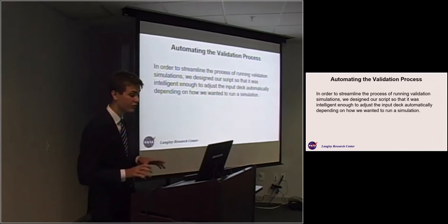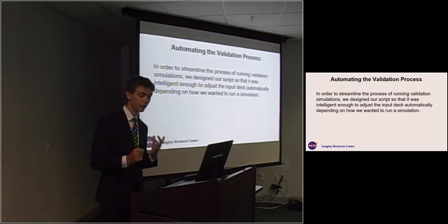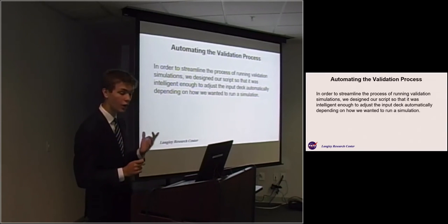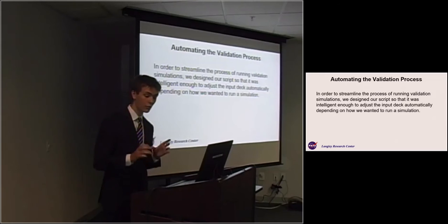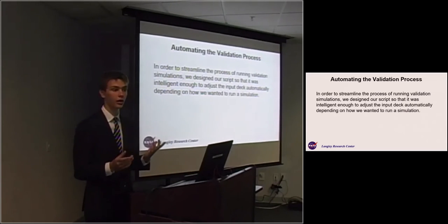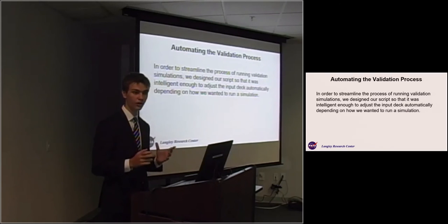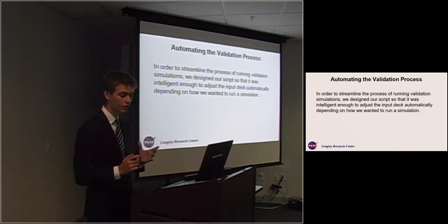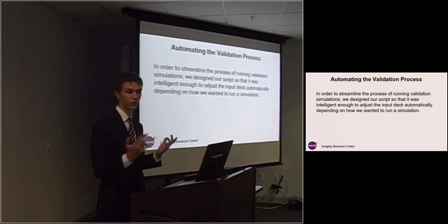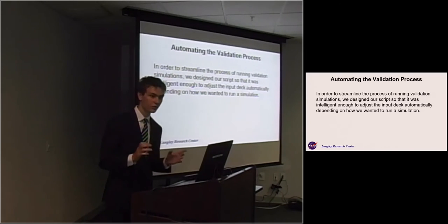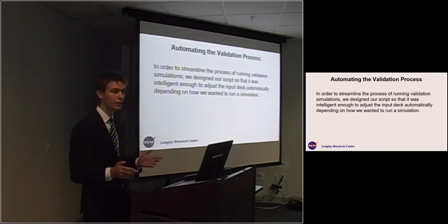In order to streamline the process, we designed the script so that it was intelligent enough to automatically adjust the input deck. So imagine we were trying to run a case called the turbulent plate case, and we were trying to validate the Spalart-Allmaras model, right? So we run our case, all good. Then we decide that we want to run the same case using a different model. Maybe we use Menter SST.